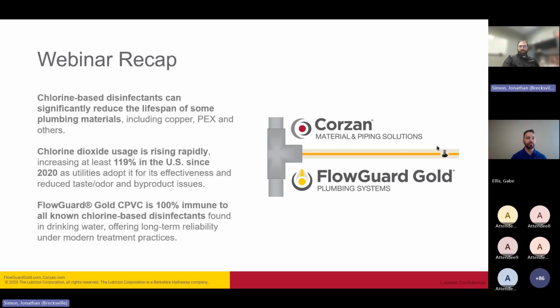Excellent. I see the one here from Ryan asking if at temperatures below 140 degrees, is there any concern with degradation in PEX tubing? So the short answer is you can have degradation at temperatures below 140 if you have those higher pressures and or those higher ORP values.